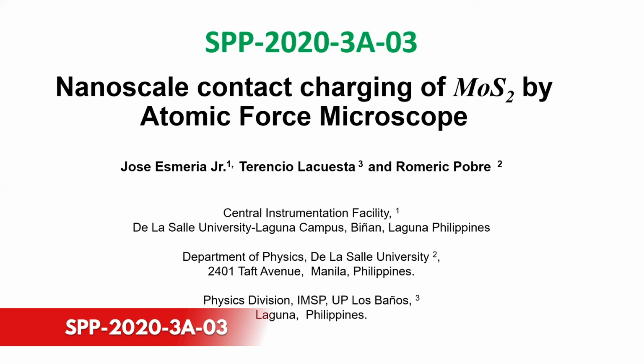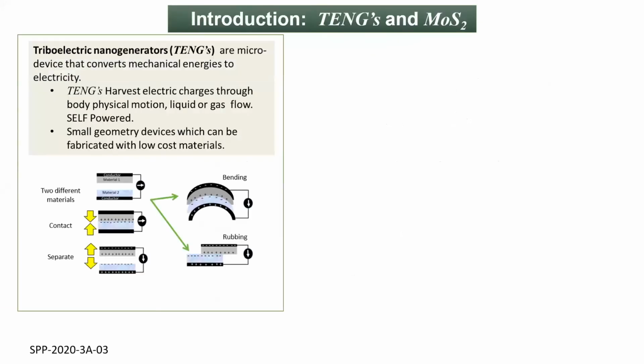Hi, I am Ismeria, one of the co-authors to present this paper on nanoscale contact charging of molybdenum disulfide by atomic force microscope. We took interest in molybdenum disulfide because of TENGs. TENGs, or triboelectric nanogenerators, can convert mechanical energy into electrical energy by means of contact, rubbing, or bending. These are low-cost materials that do not need an external source.